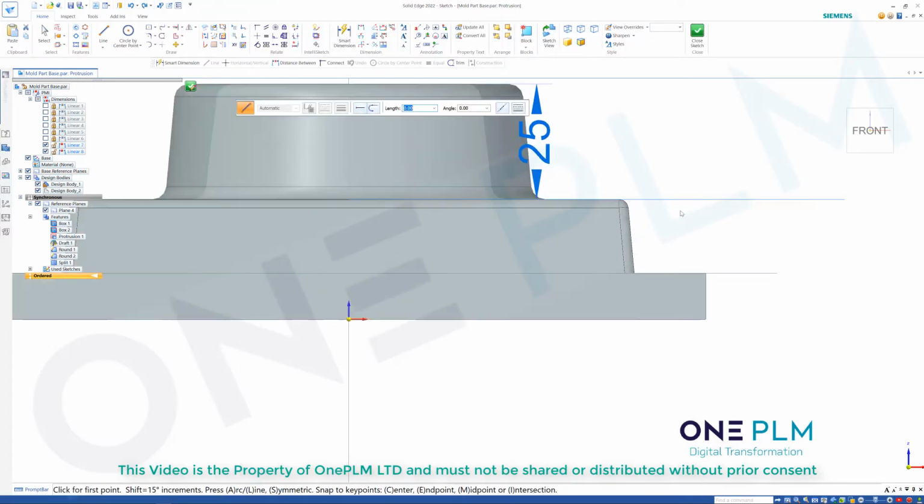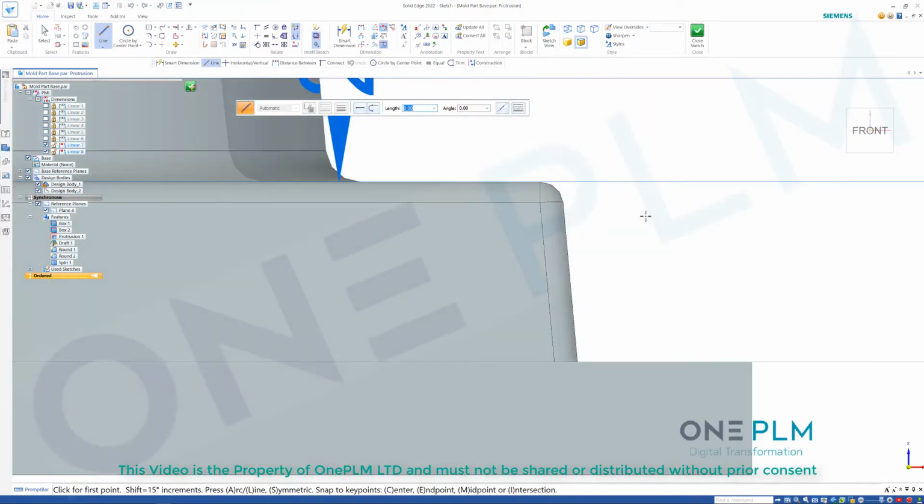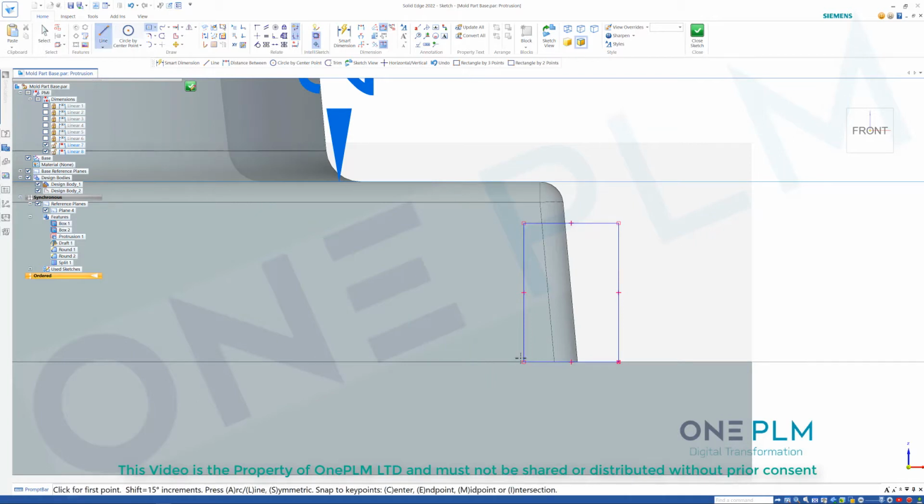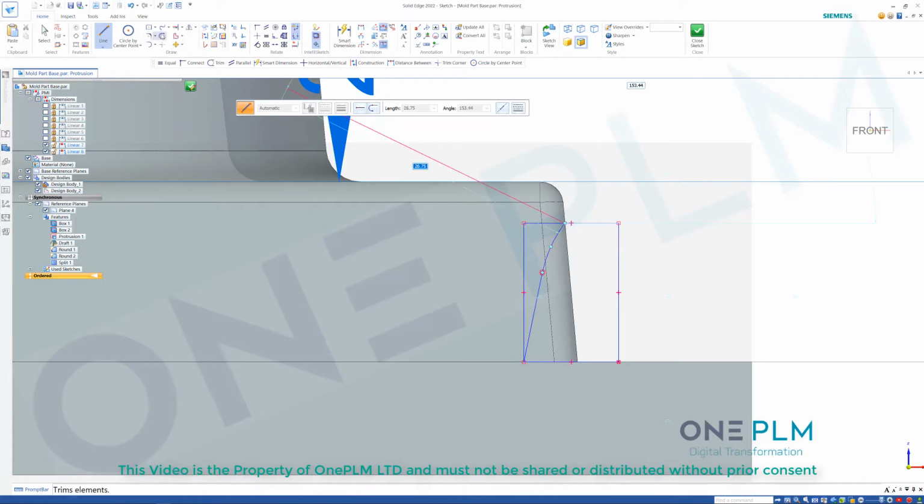And then draw the appropriate profile that we want on here. So I've actually done this slightly differently to what I was intending, but that's fine. So I want to do a box. I want to do a line coming from this corner. So it helps if I click the line command. Coming up from there, then I'm going to press the A key and do an arc, and I'm going to come to that intersection point. So if you hover over the edge and hover over that line and go to there, you'll see you've got a little cross symbol by there, showing that I've then got the intersection point.